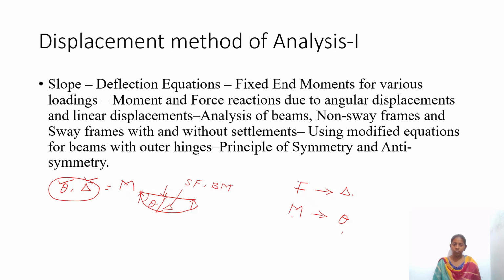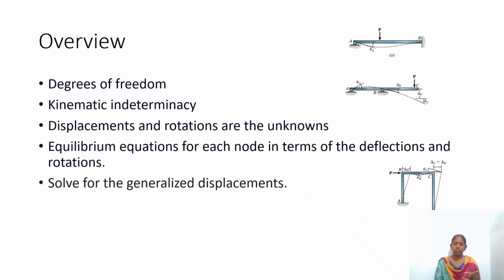So now coming to this equation. This moment equation consists of delta and theta. That's why it is called a displacement method. So the moment distribution method as well as slope deflection method as well as stiffness method are displacement methods. Force methods are the flexibility method and some integration techniques also come under force methods.